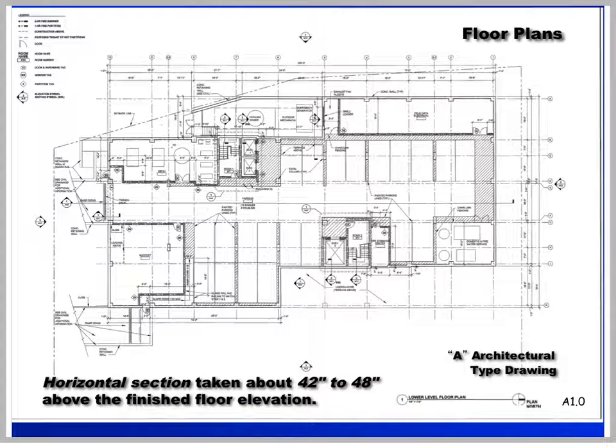Note on this drawing, we are looking at the lower level floor plan for the garage. You will find many dimensions, as you can see the basic layout of the column to column dimensions across the building. You will also find many section cuts, as you can see here, an elevation cut right there, a section cut, directing you to another page on the drawings. And again, also notice Plan North. Plan North down here is off to the right-hand side of the page.